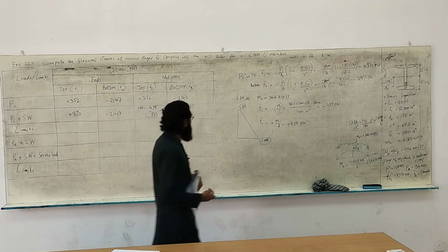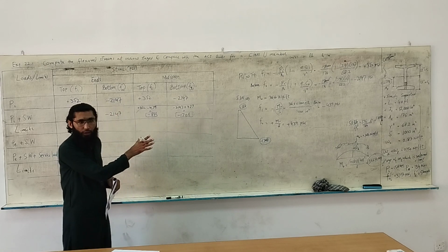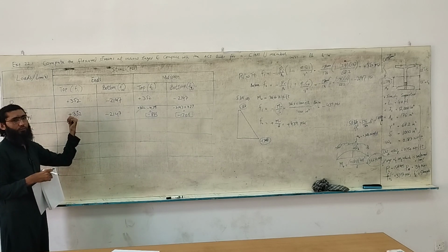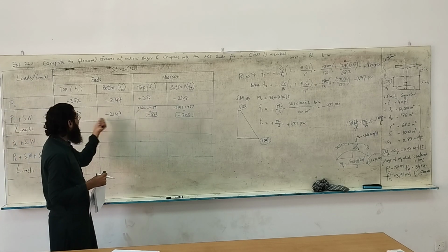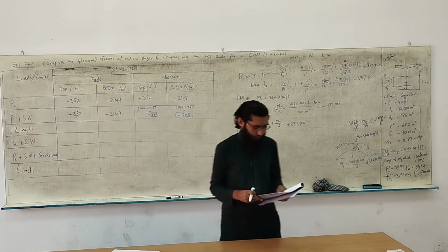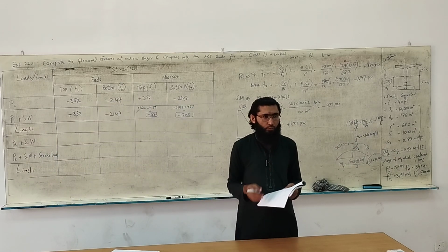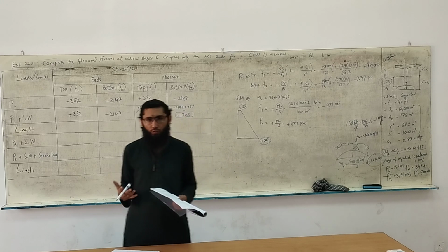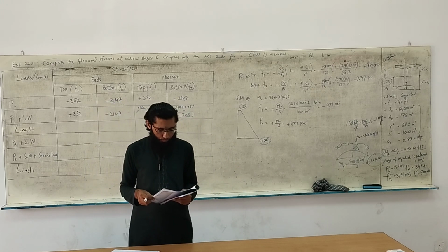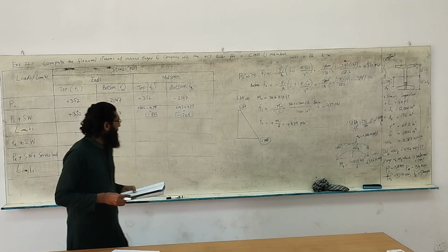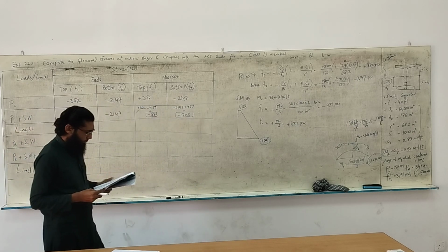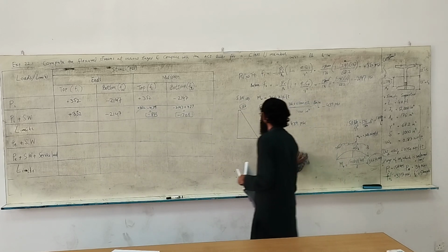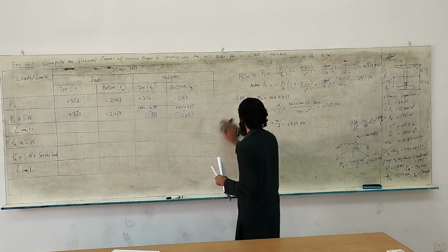But this is only happening at the midspan where the self-weight can have some effect, whereas at the ends we have some tension at the top and some compression at the bottom. There you have a unique neutral axis where your zero stresses exist. So no surprise, you can have all compression in prestressed members at certain stages. Now let's come to the limits. Please go to table 22.1.